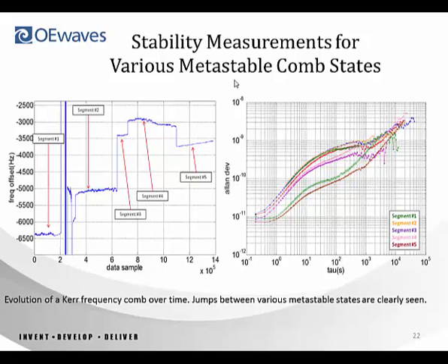If you look at the performance of the free-running device, we can see that if we just put the laser into the proper position, with proper detuning and proper power, there are many regimes. The system runs for several hours and then jumps to another regime with slightly different radio frequency. It keeps jumping, and finally it jumps out of the locking range. So first of all, we need locking, and secondly, we need efficient turnkey operation just to start the device.